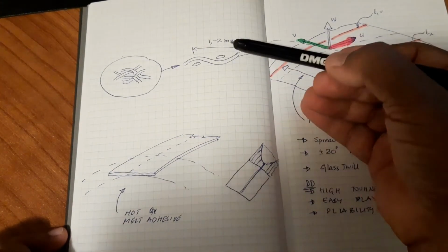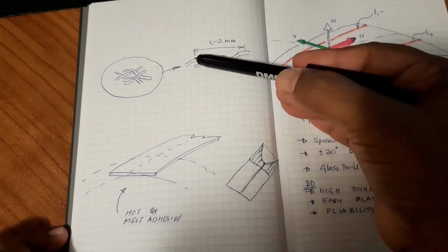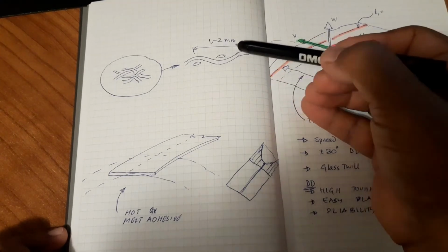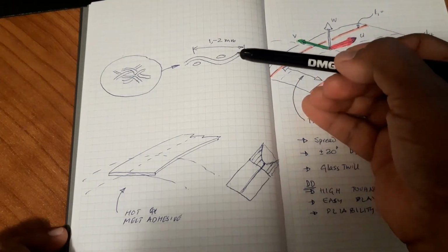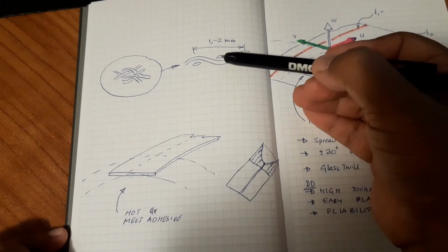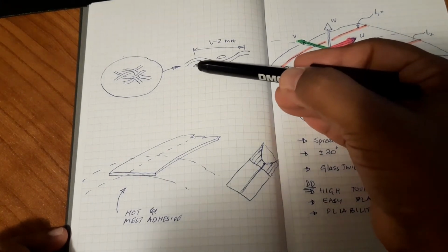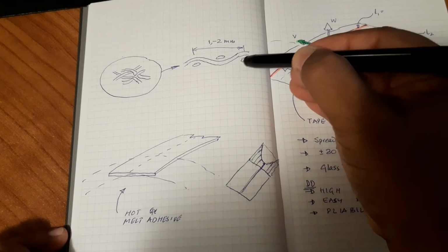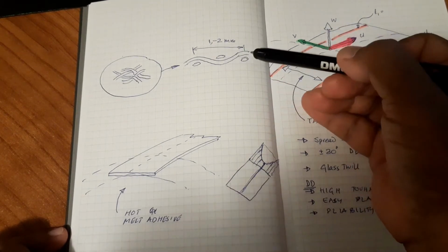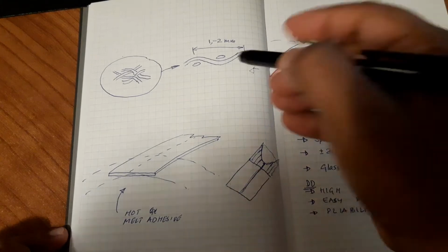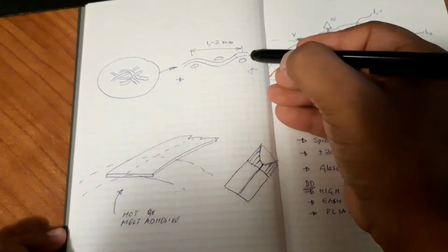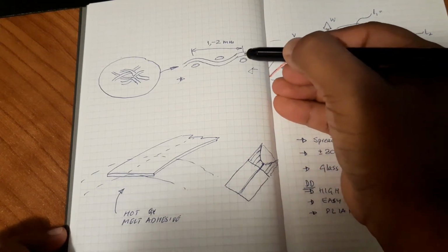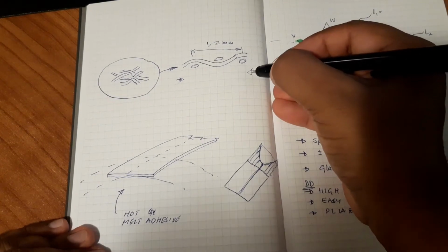And when it is woven like this, with one weft or a warp of the cloth coming with a wavelength of about 1 to 2 millimeters, because there's a piece of strand of fiber over here, there's a fiber strand here, then there's this fiber strand going up and down across those strands, and there's also a strand here. So this thing, if it is put into any kind of compressive load, it's already buckled, it's already bent. So when you apply compressive load to it, it just goes, it doesn't have any compressive strength.